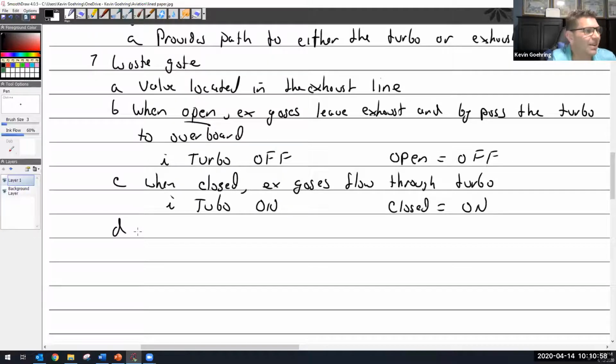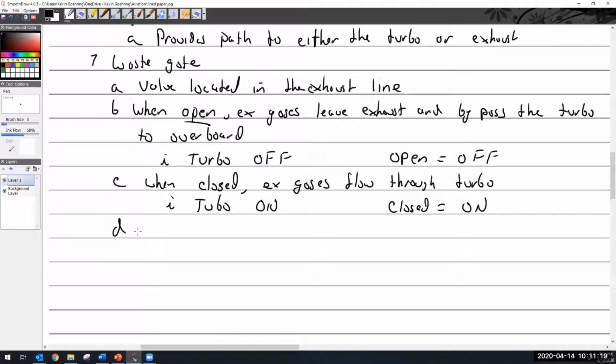And so I backed off of it, and then I heard this pow. And I'm like, oh gee, I thought I broke the whole thing. But it hit the rev limiter. And then the turbo spooled up so fast that it pressurized, and I backed off. And so it blew the pressure relief valve open, which is what it was supposed to do. So my truck does that if you're on it and then you just let off. Okay, so it's normal.